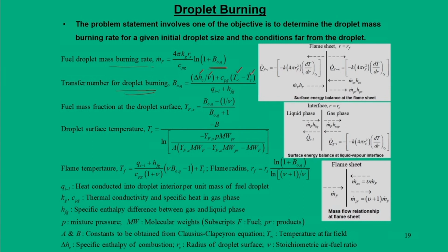TS stands for surface temperature, and the far field temperature can be up to T infinity. We can have two approximations. One is that this T infinity can be at flame temperature, or T infinity can be at adiabatic flame temperature. With this one can see the role of droplet burning, and accordingly this has a net effect in calculating the droplet lifetime.